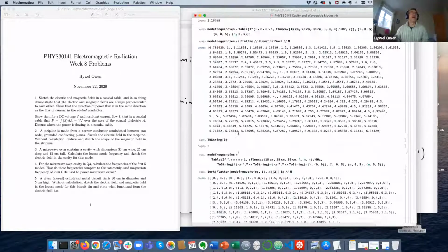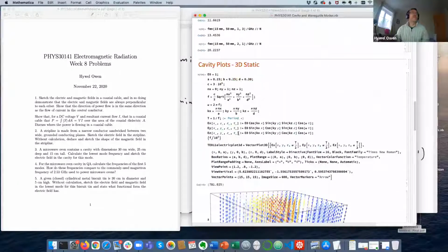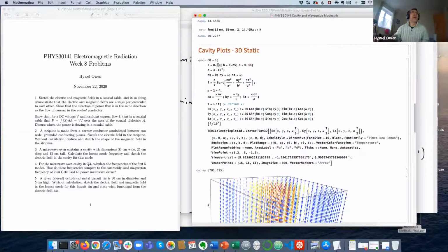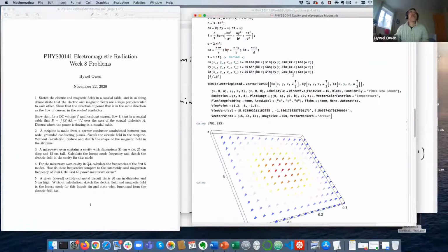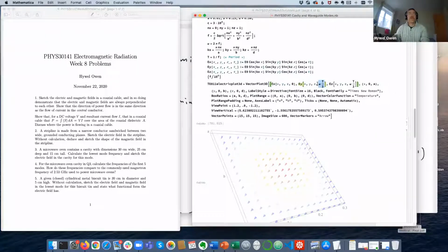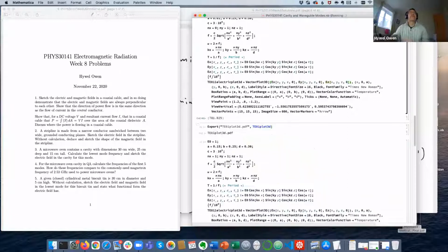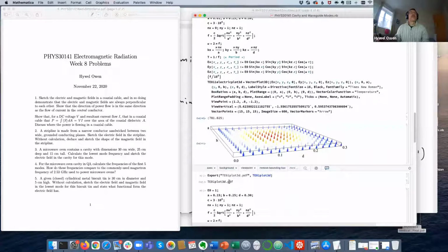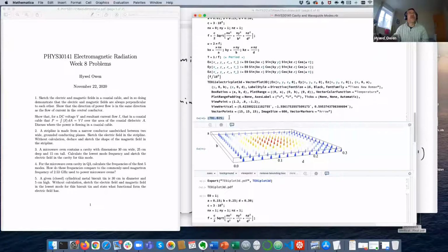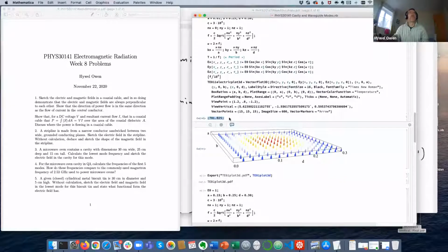So let's just plot that. If I plot that below, you can see here that I'm going to make the dimension A 1 centimeter, and I plot everything again, and I should make that equal to 0 for 0 time, so we can see. So this is 0 time, and you can see this is a very flat cavity. Okay, so the electric field again points from the bottom surface to the top surface, but it does point across, and the resonant frequency has not changed at all. That's an important thing to notice.